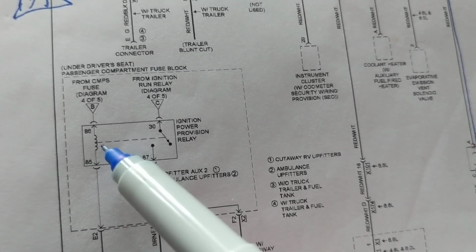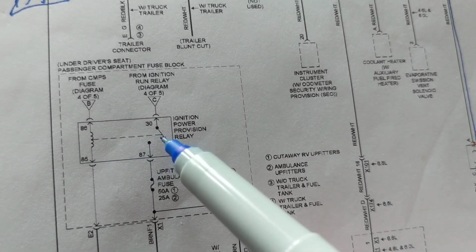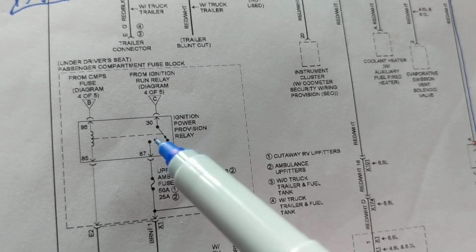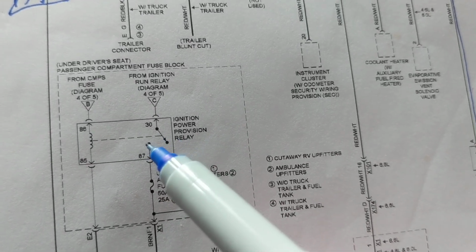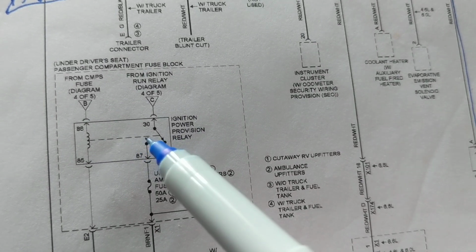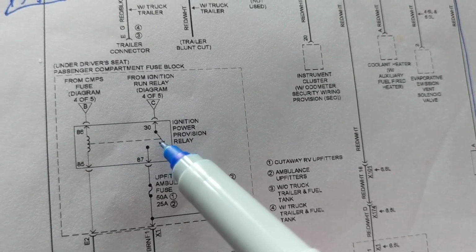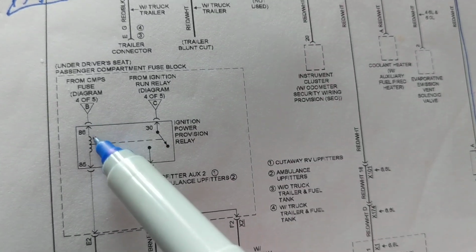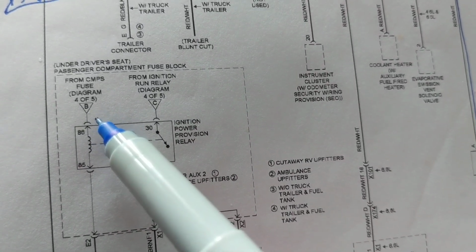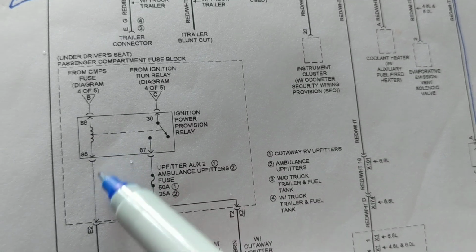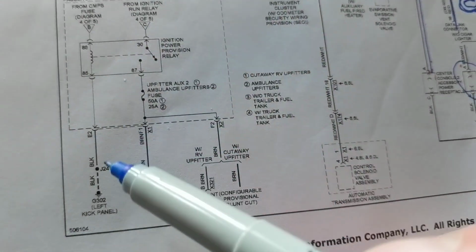It creates a magnetic field. If you see this dotted line, even if you're not familiar with relays, it tells you one thing: this pulls this one in. That's why there is a dotted line, a gang line. This tells you when this is active. What do I mean by active? I mean current is flowing through it, from 12 volts to ground.